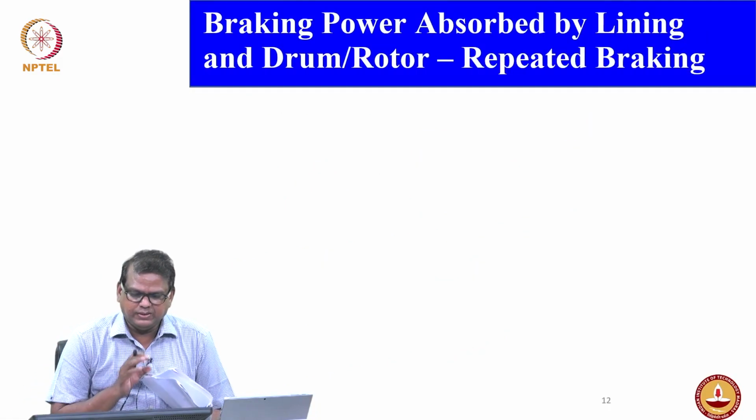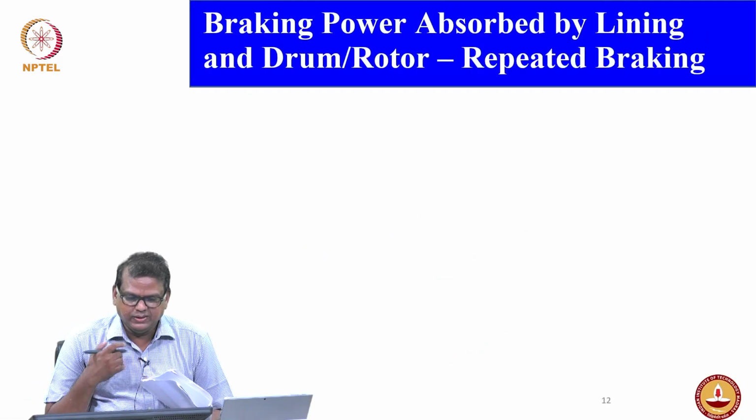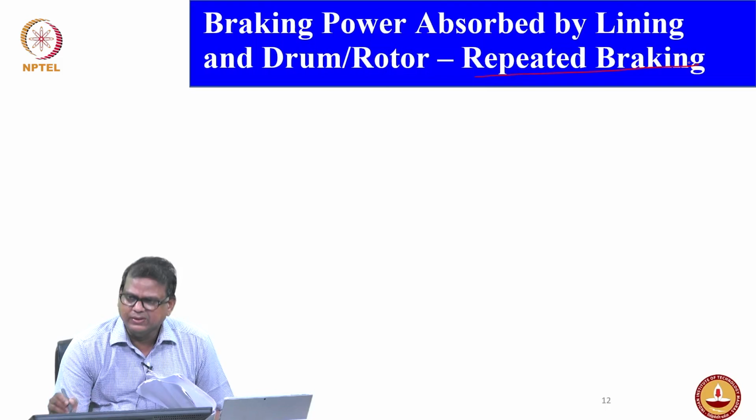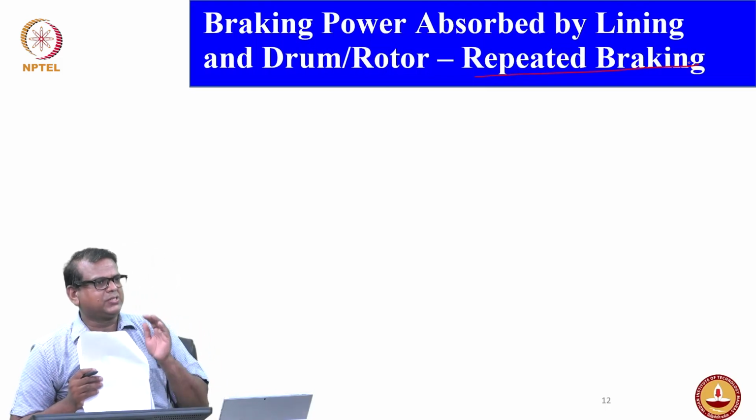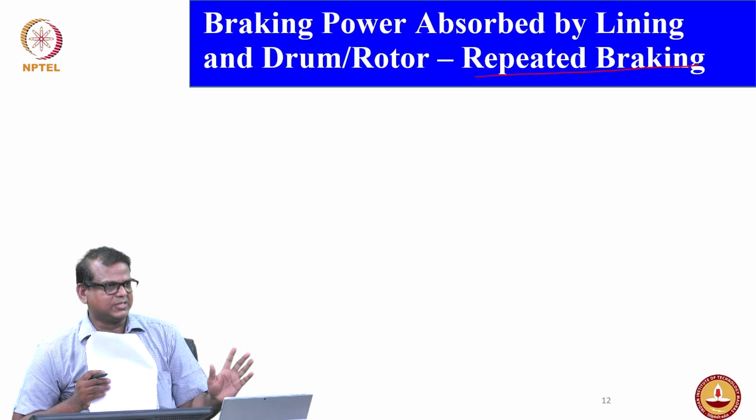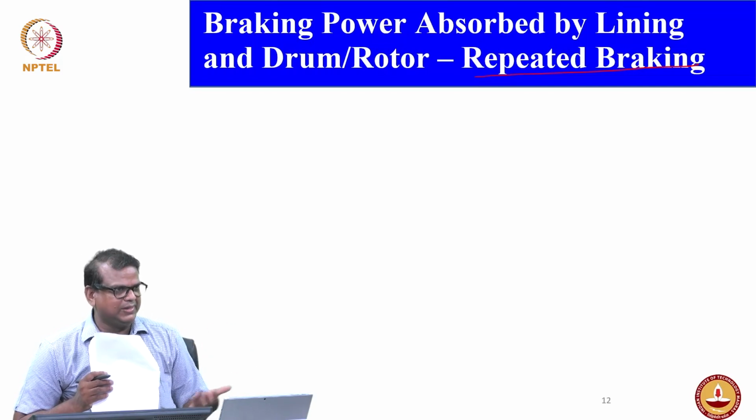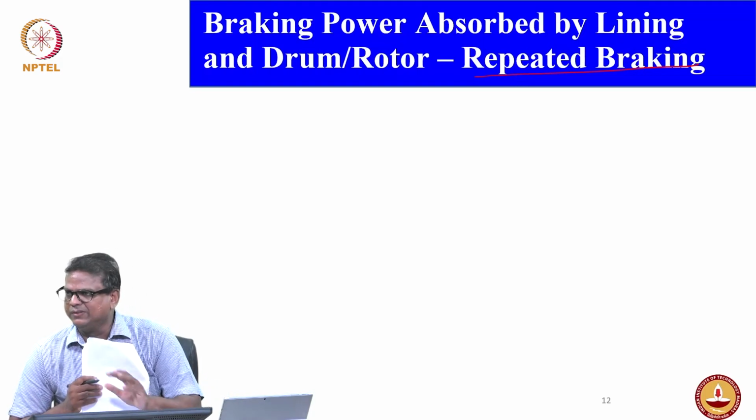Now, that is for the single stop. Okay. Now, we need to understand the brake power absorbed by the lining and drum for the repeated braking. In single stop braking, there is no heat cooling aspect. Whatever energy is developed or generated is fully absorbed by the drum and lining.